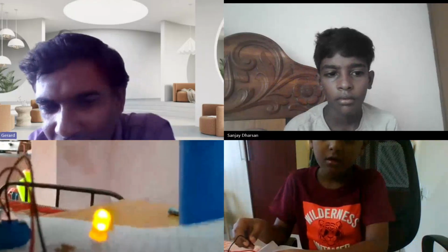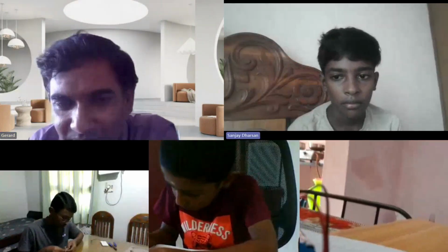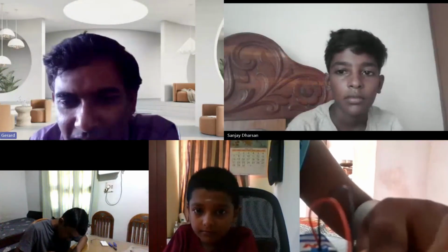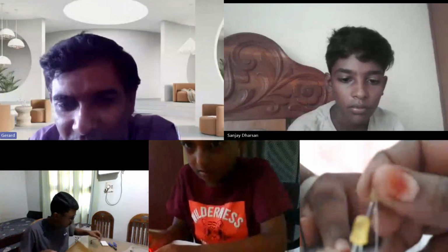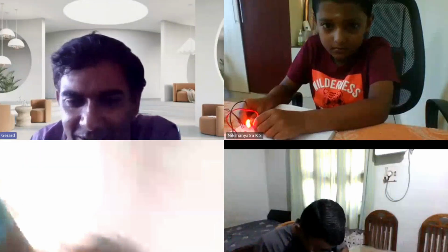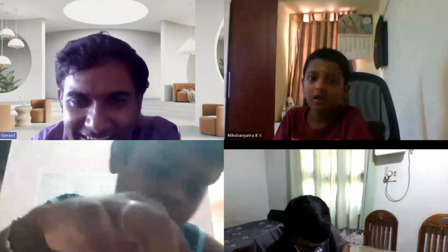It's working. Good. Thank you, sir. The other one is not glowing. Why? Connections you have to do properly, otherwise it won't glow. It might have been fused also if you're not doing it properly. The long leg is plus, the short leg is minus.